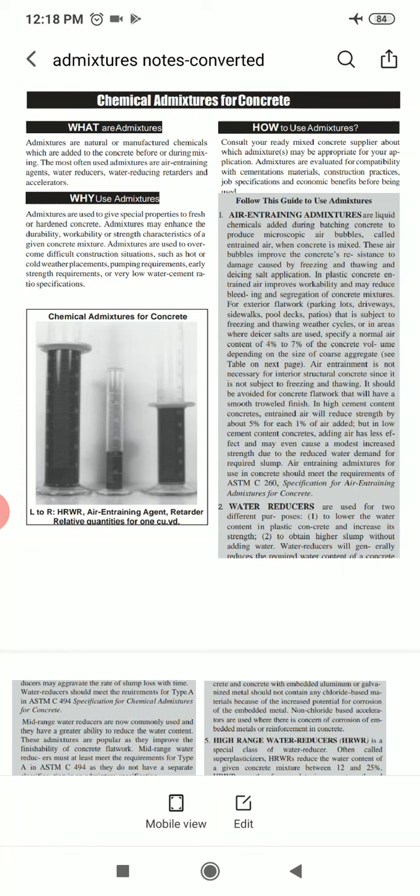But the concrete has a special characteristic that after some time it is going to set. So to prevent that, or to increase the setting time of the concrete, we add admixtures so it remains in a plastic or mobile condition. Those are called retarders.